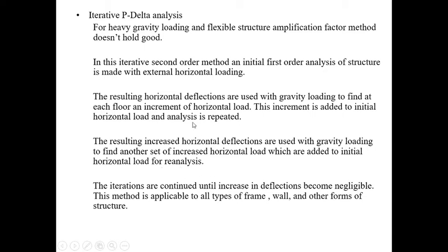You apply the horizontal load, find the deflection, find the increase in horizontal load delta H, and add that delta H again to the horizontal load. The iterations are continued until the increase in deflection becomes negligible.